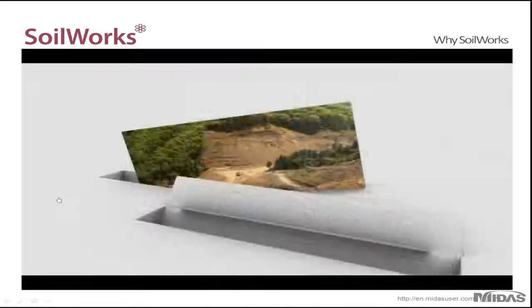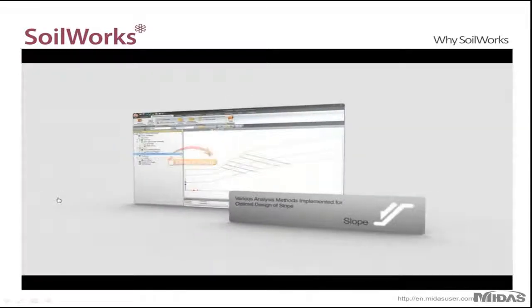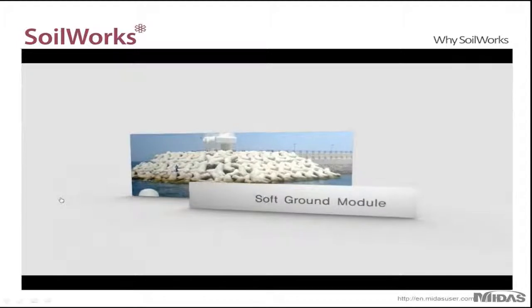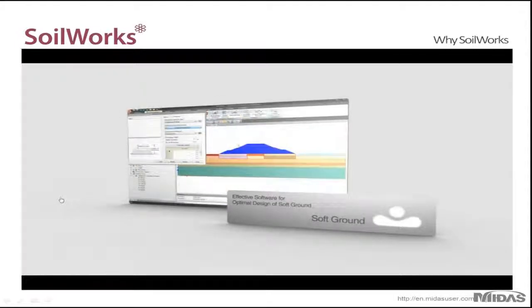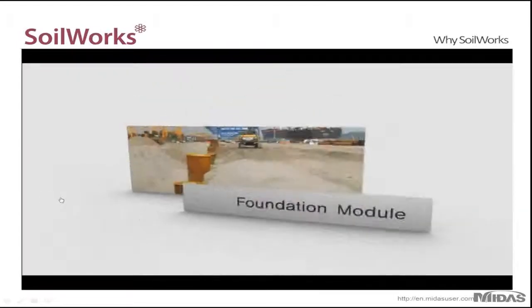And then there's the slope module for cut and embanked slopes. This module uses LEM, SRM, and SAM methods to perform analysis, and you can also get the effects of your reinforcements on your stability. The soft ground module, which is used for settlement analysis, so you can use this module to analyze the consolidation of a clayey soil over a number of years, but you can also get the immediate settlement of sandy or silty soils.